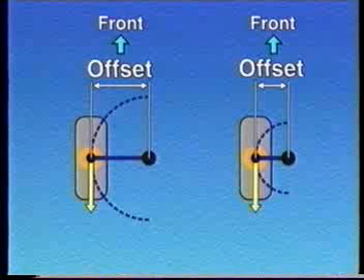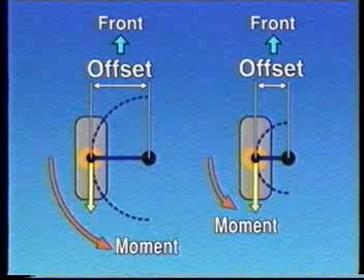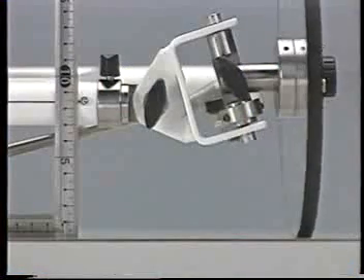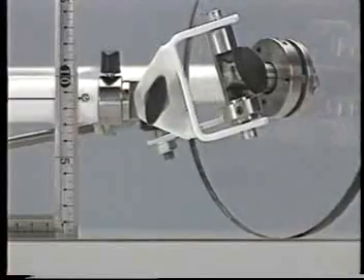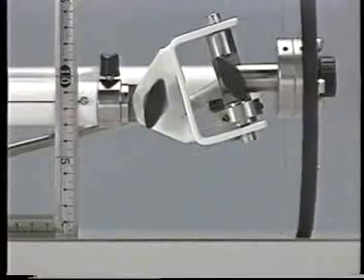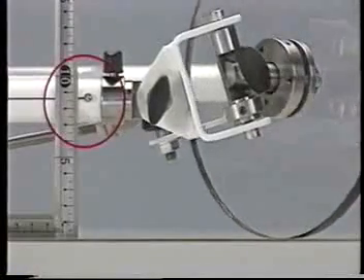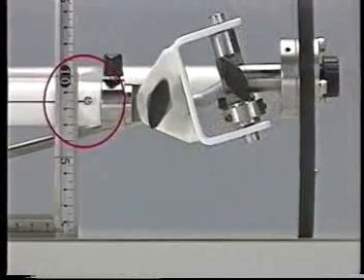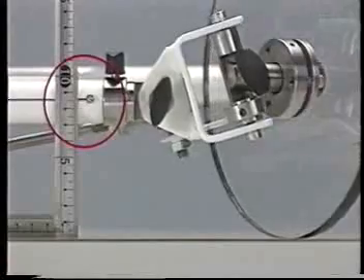When the wheel is subject to shocks caused by irregularities in the road surface, or when braking force is applied to the wheel, a moment is generated with the radius of the offset. The influence of this force on steering can be reduced by making the offset small. Moreover, when there is a steering axis inclination, the wheel raises the car body during cornering, geometrically increasing the effect of the wheel recovery force of a caster, as explained earlier. So steering axis inclination also contributes to increased straight-ahead stability.